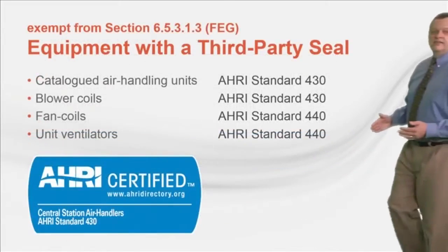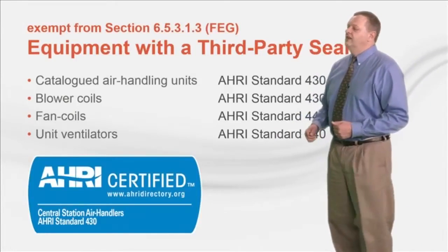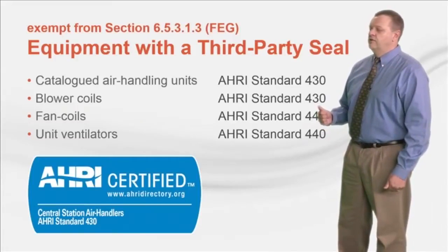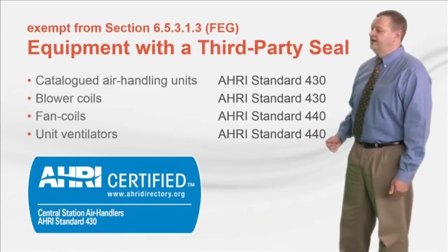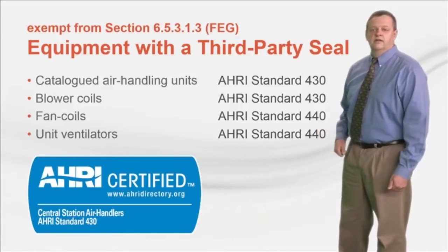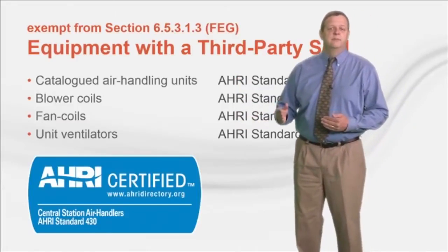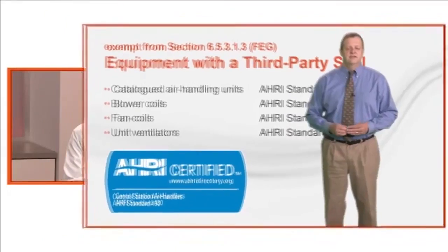Most air handling products bear a certified seal from AHRI. Cataloged air handlers and blower coils are certified to AHRI standard 430. Likewise, fan coils and unit ventilators are certified to AHRI 440. Therefore, most of the fans in these products are currently exempt from this new FEG requirement. But there is some nuance to this.